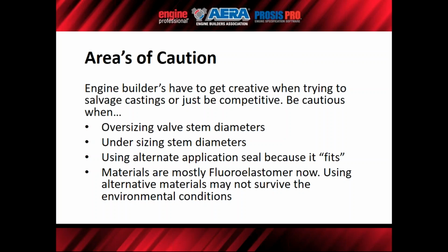It's turbocharged, direct injected. So we have to be cautious about that and validate the materials that we're going to use, or you're probably going to have some short-term failures. Polyacrylate and butyl and nitrile and so forth, those started out as crankshaft seals. You don't see too much of that being utilized anymore.